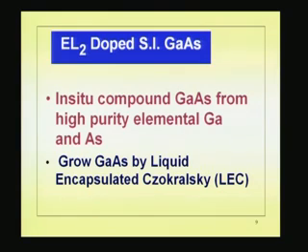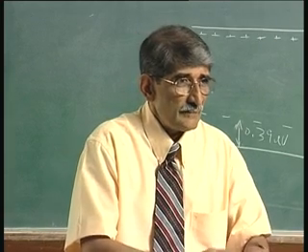Now, let us take a look at this other doping thing for gallium arsenide. What we said is, you get n type gallium arsenide with conventional doping: melt polycrystalline gallium arsenide, then grow, you get n type. That you can compensate with chromium acceptor level.